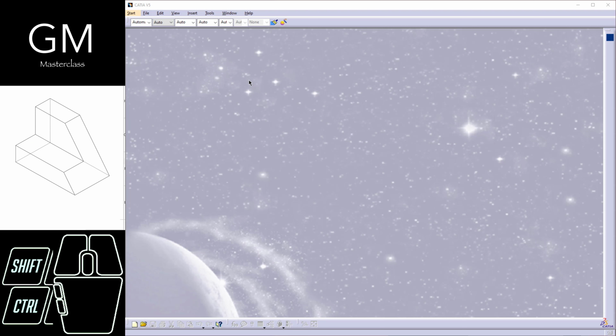And for me to start creating this 3D model, I have to see the information within the views. Right here I can see a mistake, and it's regarding this view. As you can see, this view does not contain information for me to recreate this 3D model, or if I were going to manufacture it. Why is that? Because I cannot see information about anything right here. This doesn't tell me anything.